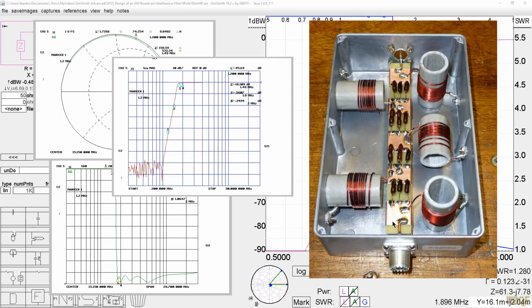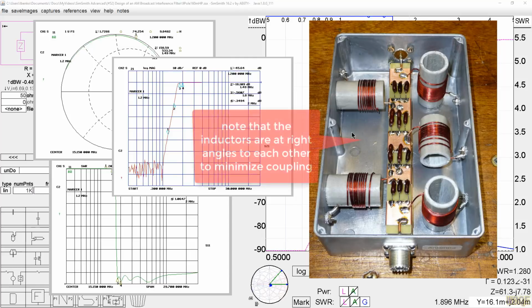With this piece out of the circuit, I went in here and measured the inductance to ground on each one of these independently with a cable I'd calibrated to the end with the lid on, and then I put this piece in afterward. And it was spot on just from the measurement. So that was a success. And it completely killed the IMD at this station, and it worked very, very nicely.